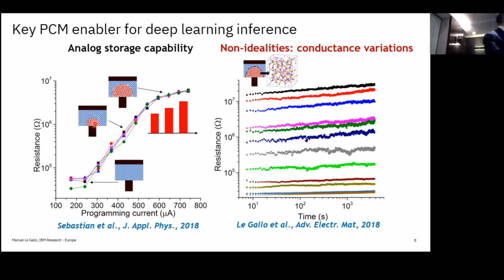Yeah, exactly. Drift is also present in ReRAM, but I think it's probably less than here. Although, as I said, drift is not the biggest issue here. The high voltage is definitely worse in ReRAM than PCM. In most of the works I've seen, they still use a forming process where you need to apply a very high voltage at first on the ReRAM to make it operable.